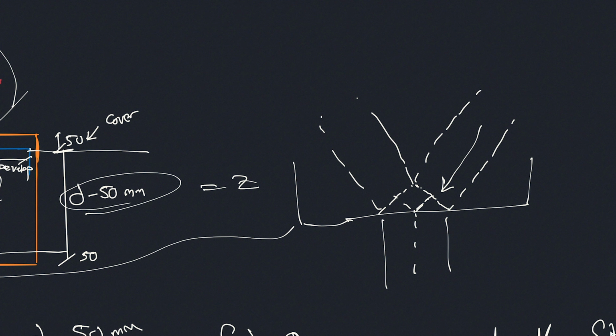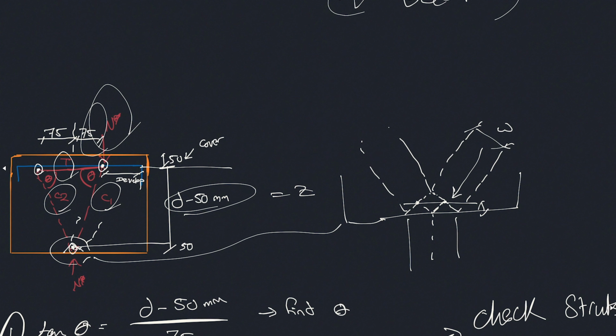So for the center of the node, we're just taking it at the face over here. You can work out this distance in great detail once you know the width of your strut, but you don't need to overcomplicate things because it's within 25 to 50 mil. If you want to overcomplicate things, that's fine, it's up to you. But if you're just designing it, and as always with structural engineering, if it's within 3 to 5%, you know it's safe and it's generally going to work. So don't overcomplicate things over here.